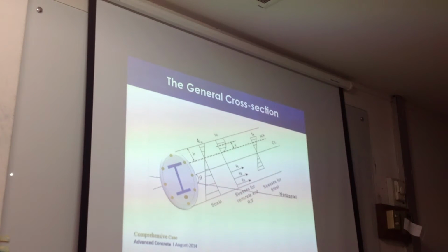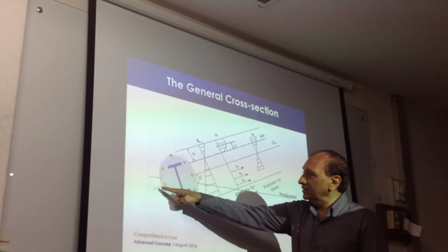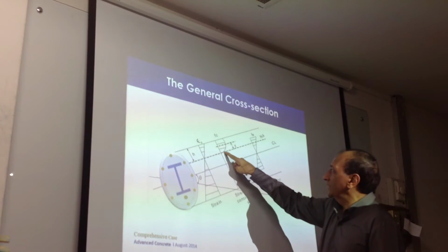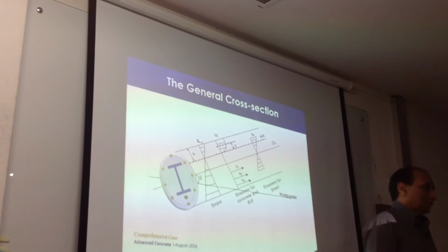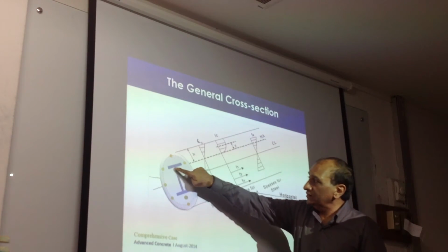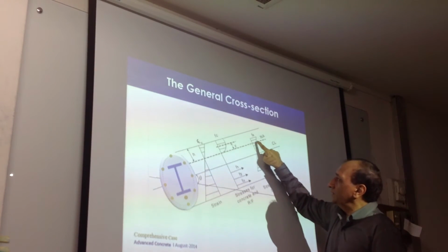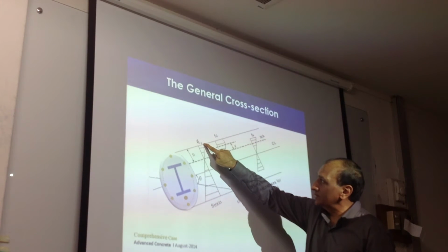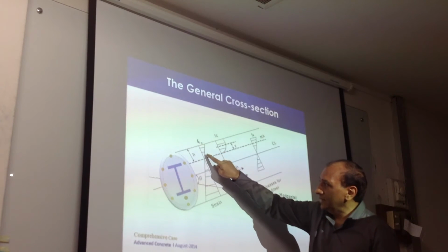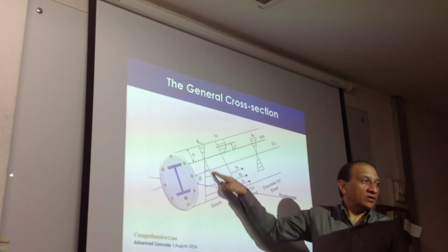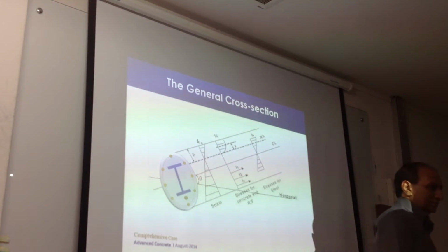So far clear? Then we say, okay, this line, let's say this is our neutral axis somewhere here, this dotted line. What is a neutral axis? We will talk about that. In fact, there is no such thing as a neutral axis, but okay, let's say that there is a neutral axis, right? And based on that neutral axis, there is going to be a strain. So there is going to be some strain here, compression strain and tension strain, correct? So this is the strain diagram of the cross section, assumed, correct?